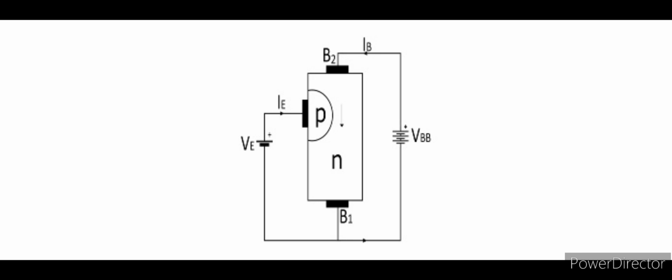From the previous case, we already know that a part of voltage VBB has caused reverse bias between the terminals emitter and the base B1. So now as soon as we apply VE, the device doesn't get on because there is an existing voltage V1 that causes the reverse bias of the junction. So reverse bias gets maintained until VE is less than V1. When applied voltage crosses V1, the junction becomes forward biased.